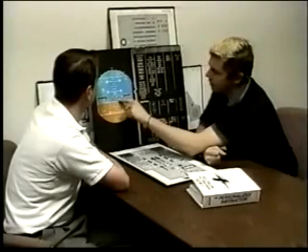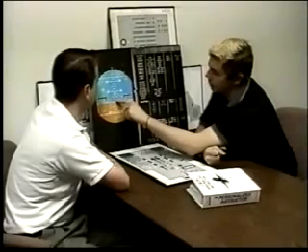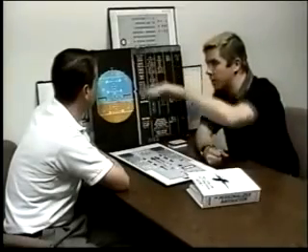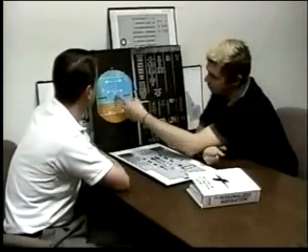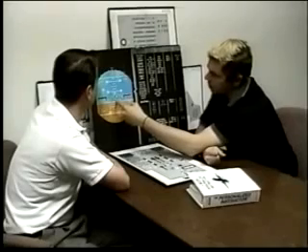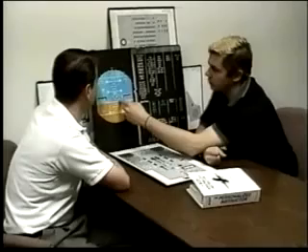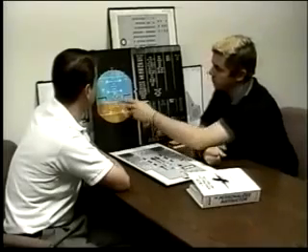Right now, the flight path vector, because it's above the horizon line, about 1.5 degrees, means that our flight path from the horizon is climbing 1.5 degrees. Also, because it's to the right of the center line, that means we are drifting to the right, and we must be having a wind from the left side.